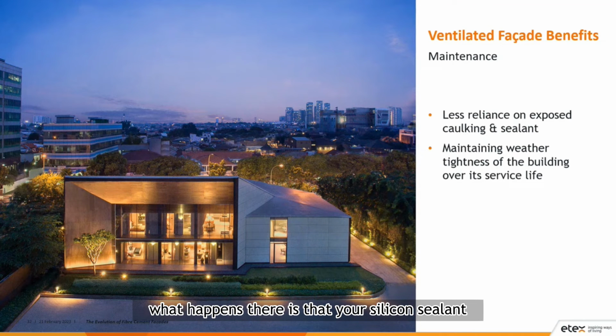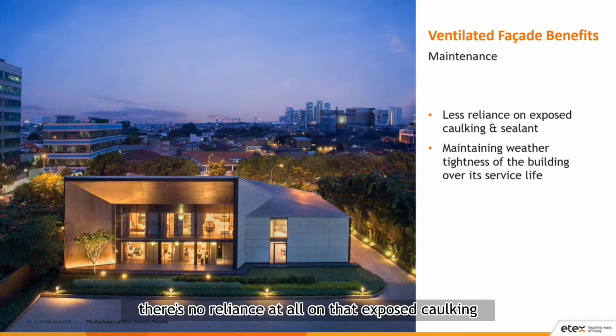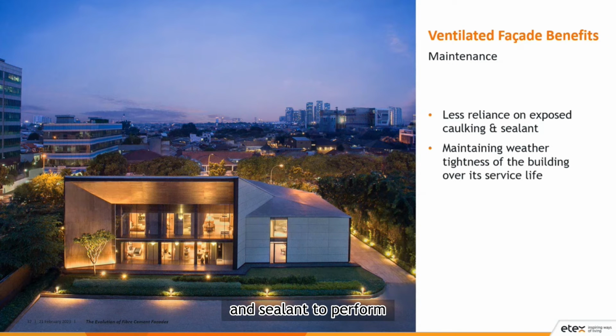What happens there is that your silicone sealant, your caulking does need to be maintained. It will get brittle over time and fail. So it does need to be maintained. With a ventilated facade, there's no reliance at all on that exposed caulking and sealant to perform.